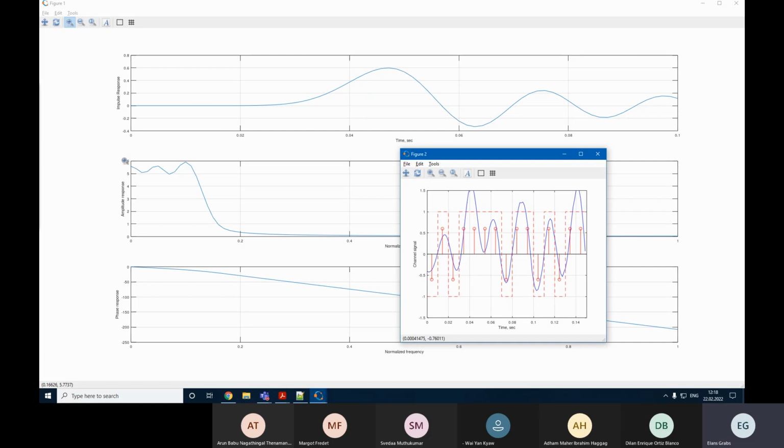Yes, because here we have actually almost hit zero. Here we have also come very close to zero, and basically all the points are smaller than they could be, except maybe here we were lucky. Here we were extremely lucky because, well, we are stronger. Here also. But this has happened actually, you know why? Because inter-symbol interference is the effect when previous symbols affect current symbols. Here, however, as you can see, we had 4 symbols of 1 in a row. Still, this was not enough to save this symbol, so it doesn't automatically mean that everything is fine. Yes, it's a quite complex situation.